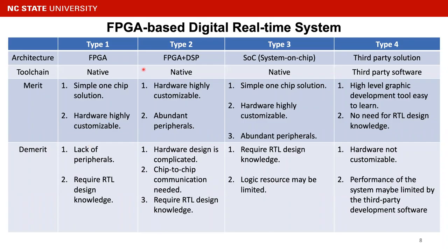Secondly, we have the FPGA plus DSP architecture, which also has highly customizable hardware and abundant peripherals from the DSP. However, the hardware design is complicated and chip-to-chip communication might be needed. Also, it requires RTL design knowledge.